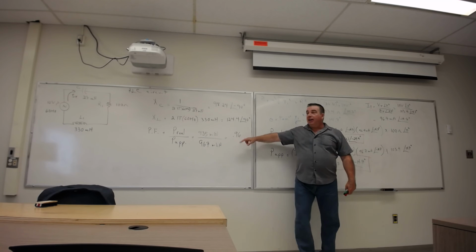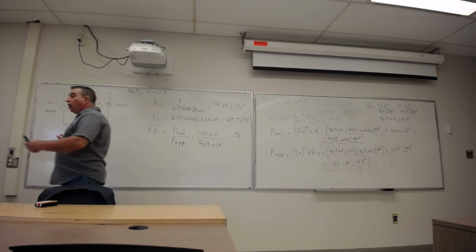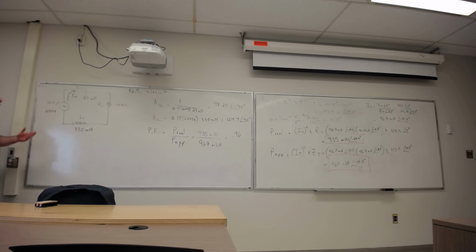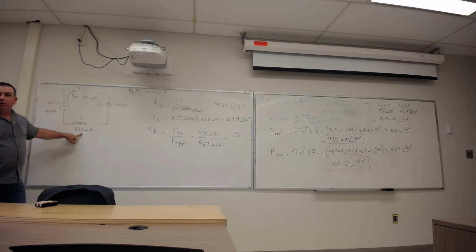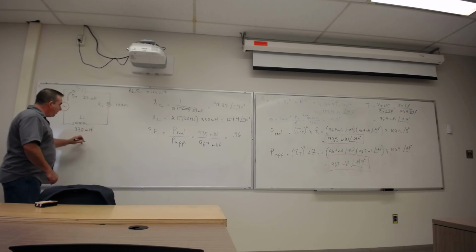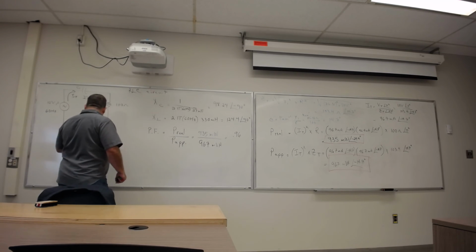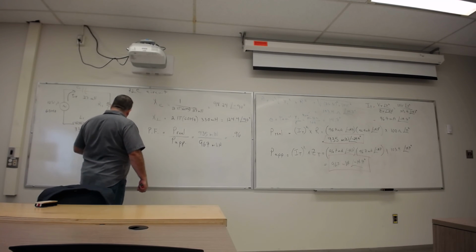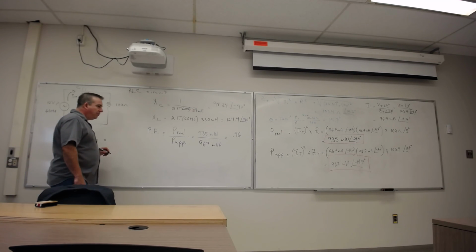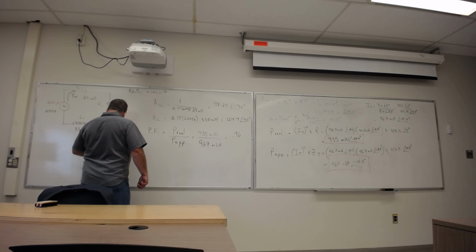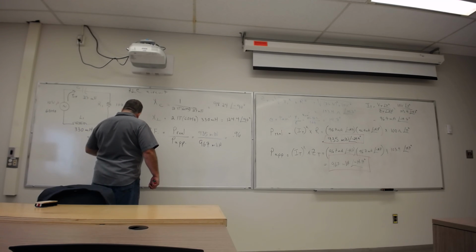And in fact, what you can do is calculate what's called the resonant frequency, and you can figure out the exact value of capacitance that's going to null out this inductor. There's a little formula, I'll give it to you if you're interested. It's called resonant frequency. F resonant is equal to 1 over 2 pi the square root of LC.